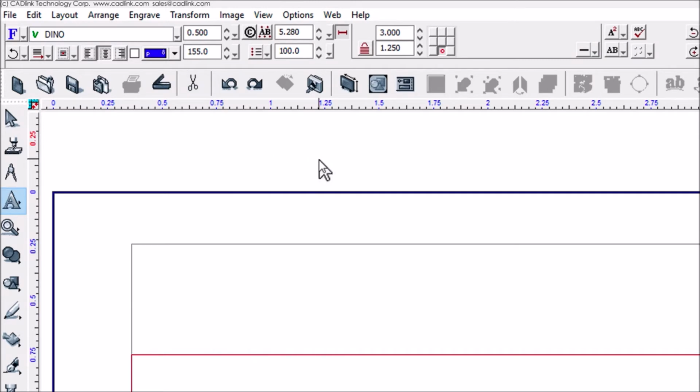In the Smart Bar, set the text frame properties according to how you need the text to be applied, keeping in mind that you probably want some text compression settings for situations where the replaced text would otherwise exceed the badge dimensions. To give you an example of possible text frame properties to consider, we set the following. For the font height, we set 1/2 inch. For the line spacing, we set a relative spacing of 155% of the font height.